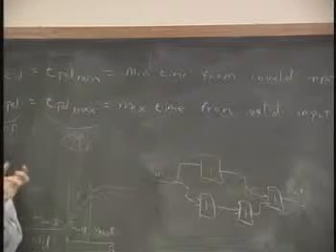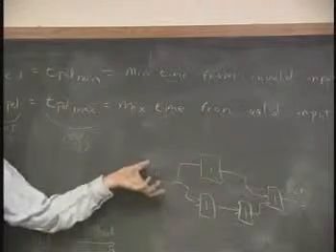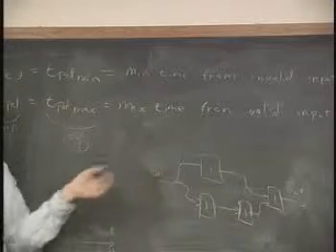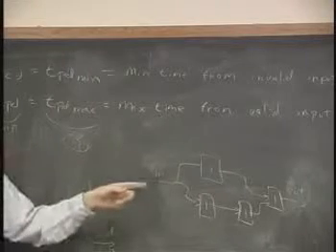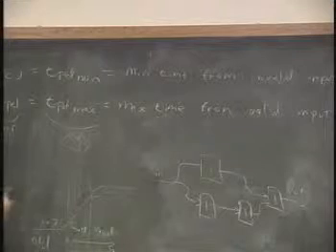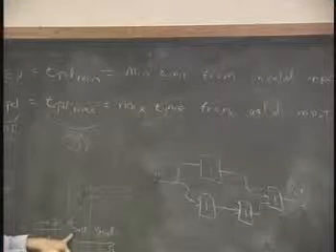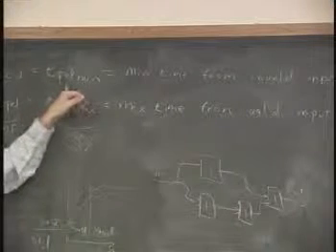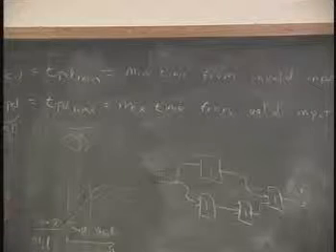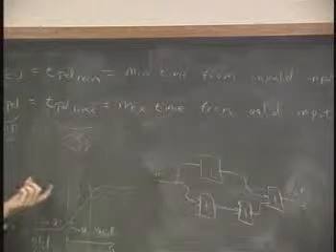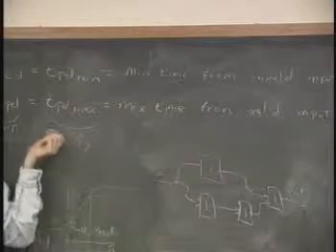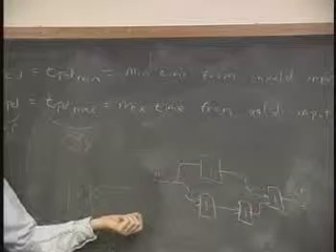But it turns out that in designing circuits that do timing on the data that flows through here, when we're worried about how fast data goes through, the TPD min, we actually are concerned about how fast invalid data goes through. So that's why, in general, TPD min is a measure of the invalid time on input to invalid on output. Whereas when we're worried about how long it can take at most for the data to go through, we care about how long it takes the valid data to go through.